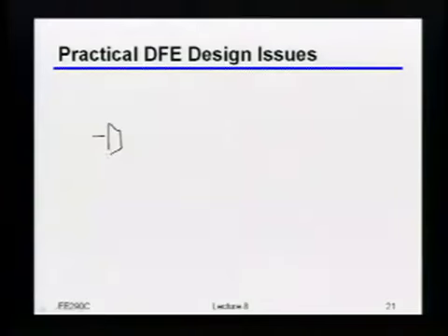So just to give you an idea of what that looks like, I wanted to quickly draw what a two-way interleaved DFE design, sometimes called DDR, which stands for double data rate, might look like, at least just for one tap. Okay? So if you did something like that, you might now have two independent summers.